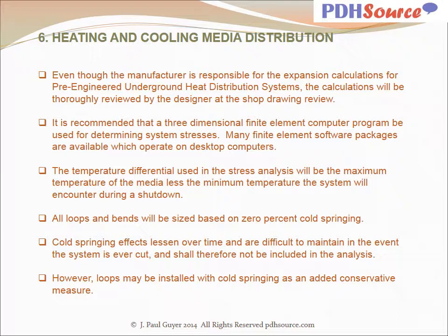All loops and bends must be sized based on 0% cold springing. Cold springing effects lessen over time and are difficult to maintain in the event the system is ever cut, and shall therefore not be included in the analysis. However, loops may be installed with cold springing as an added conservative measure.